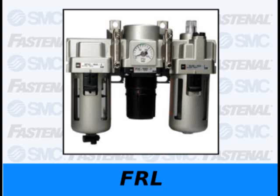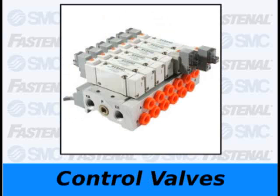The regulator in the middle adjusts the pressure to what is needed for the specific process, and the lubricator on the right is not used as much today as it once was. Virtually all of SMC's components are permanently lubricated from the factory, so they don't require any additional lubrication. Hand tools, however, like air wrenches or sanders, usually require lubrication, but otherwise you may just see the filter and the regulator without the lubricator. Be sure to recommend an OSHA lockout valve too.